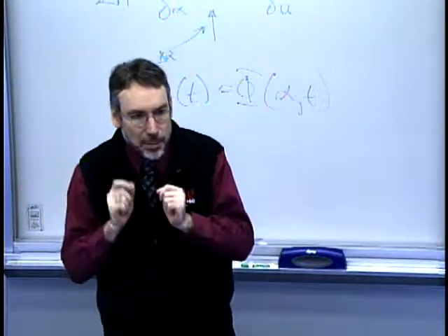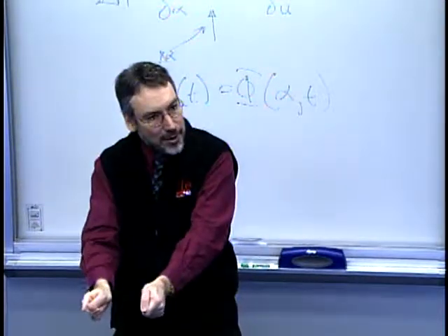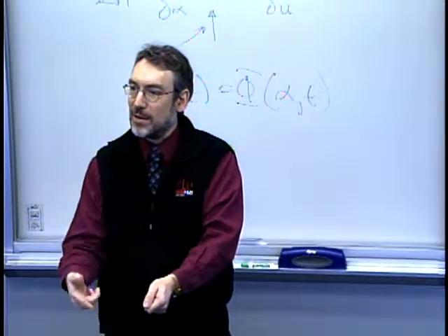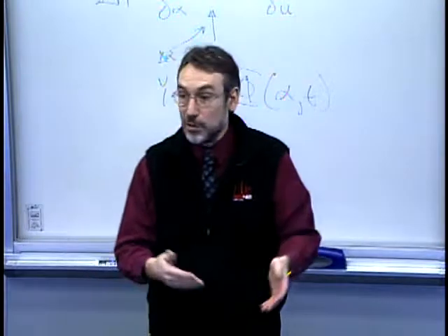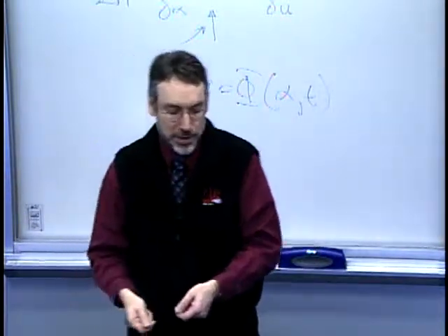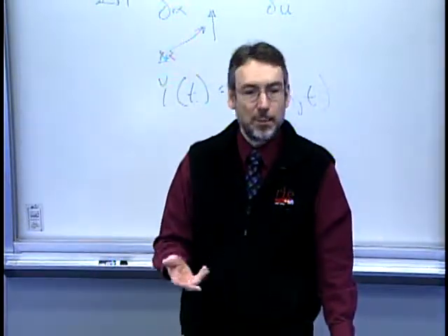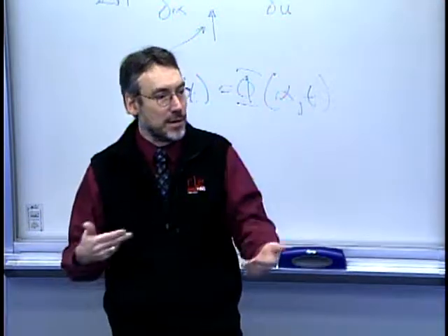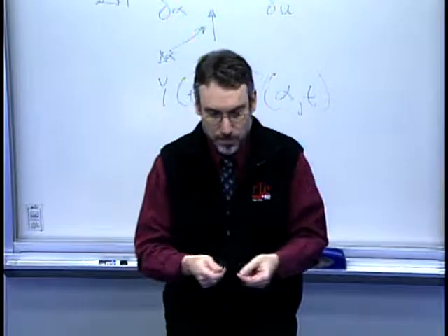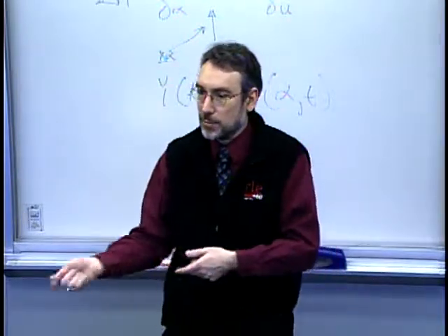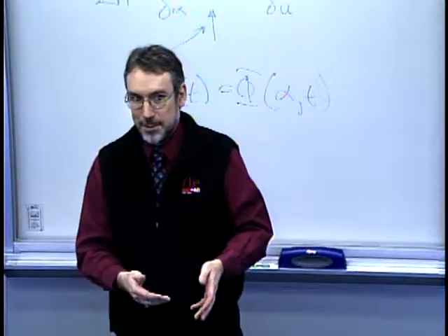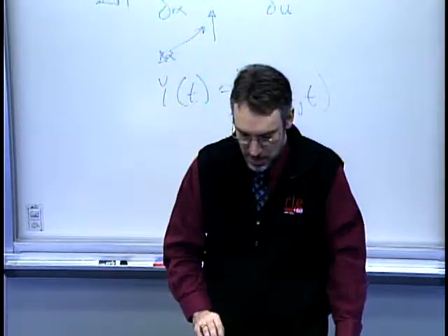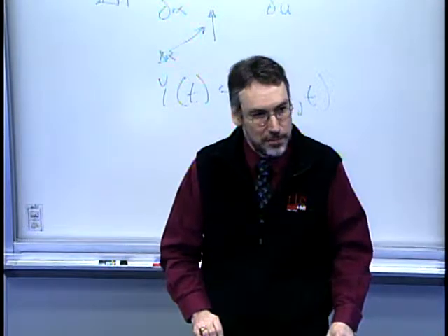And then there might be a separate component. If I pulled that same part out, took it out, and put it back on, and did that sequence of operations, including the operator operations, then you have a reproducibility component that might be, in fact, much larger. So you'd need to understand and maybe decompose and break down those different components. And then if you started to see that one was the source of deviation, then you might look at strategies to control or compensate for that. Yeah.